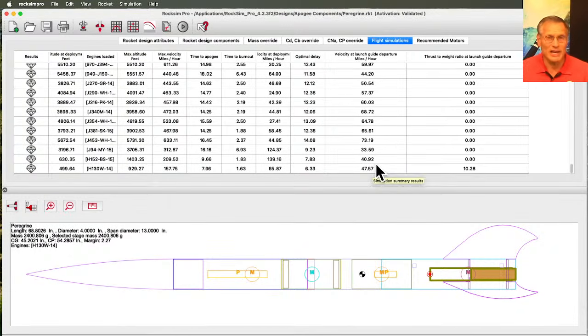And I like that better than thrust to weight ratio because when you look at that number, it's like, what thrust are you talking about? Because the rocket motor's thrust varies over the burn time. On some rockets, when it first ignites, it may have high thrust. And on some rockets, it might have a low thrust and then gradually increase over time. Looking at the number on the rocket motor case, you don't know.